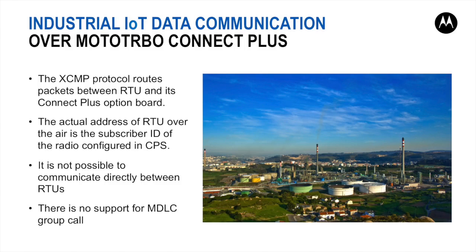The MDLC time synchronization should be avoided because of the long delays added by the radio or repeater. NTP is also not supported, as it is not an IP-based communication. There is no support for MDLC group call on Connect Plus. Hence, trying to transmit a group call will result in it being replicated and sent to each RTU.